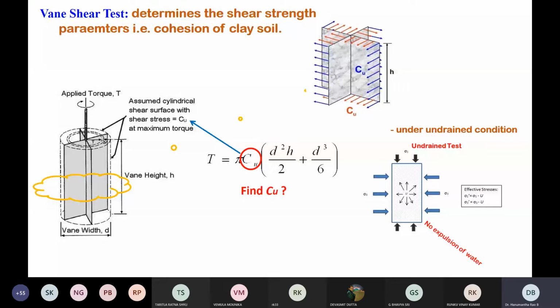In an undrained condition, the water molecules also carry some amount of load. In case of the drained condition, as the water molecules cannot take the load, because of the application of the load, they will go away, with the equivalent property, that is permeable.